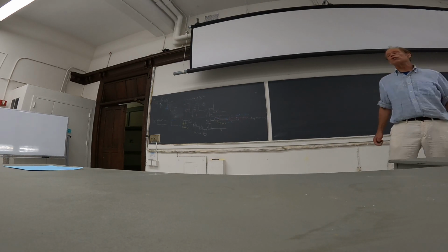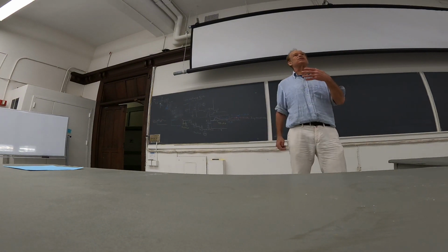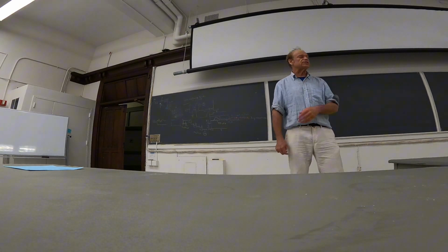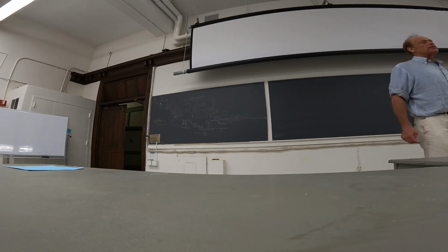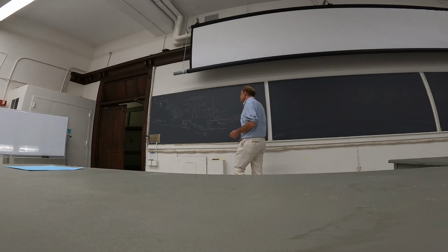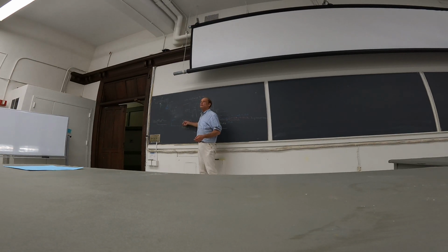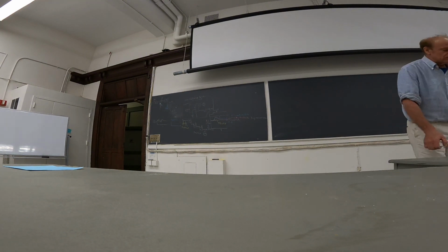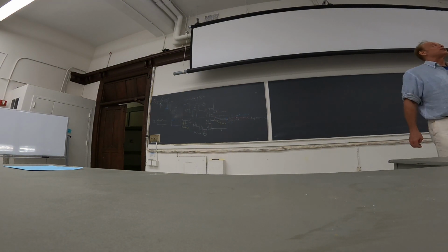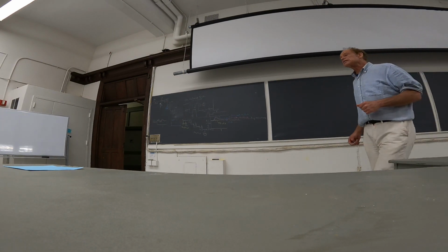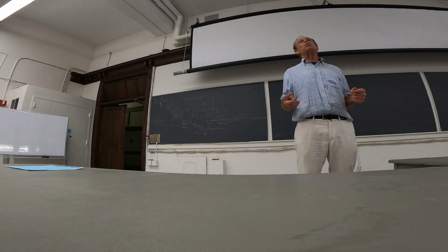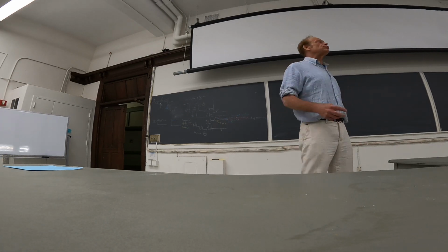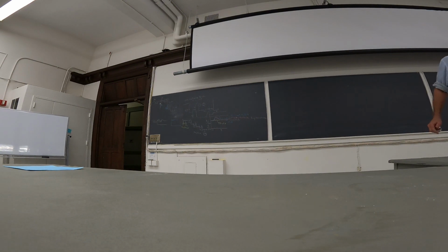So in order to actually understand these things, to know how to take the output of the measurement and turn it into and control the manipulated variable, you need a model. And there are various types of models. So, for example, there are theoretical models and experimental models. Sometimes the system is so complicated that you may want an experimental model. And I believe you would have spoken about this in your 341 in fluid mechanics class.